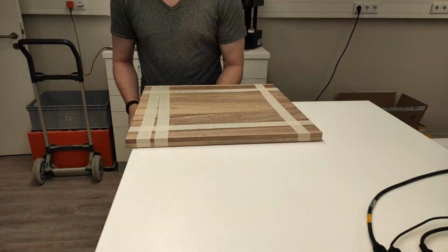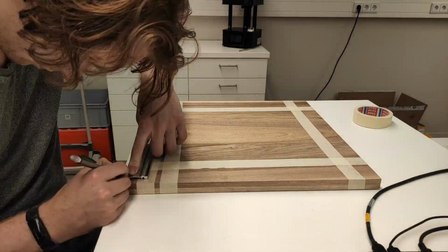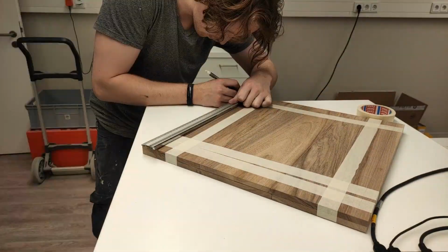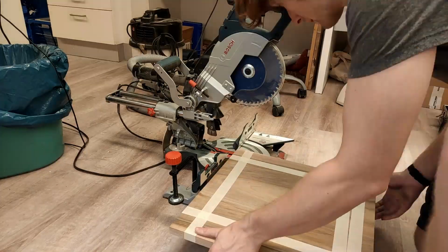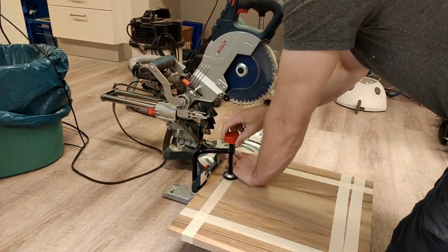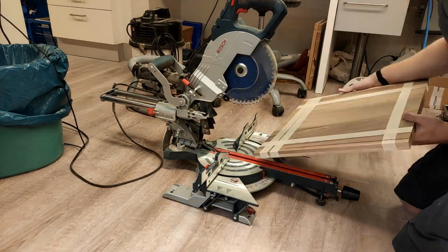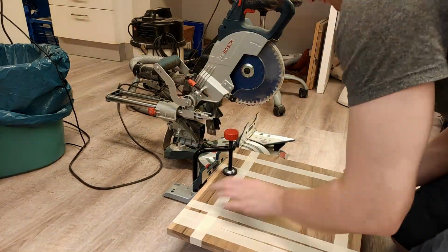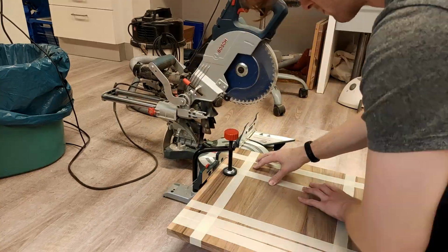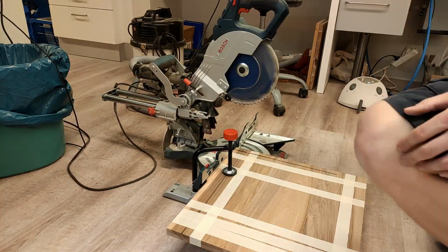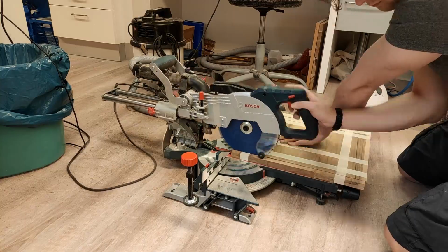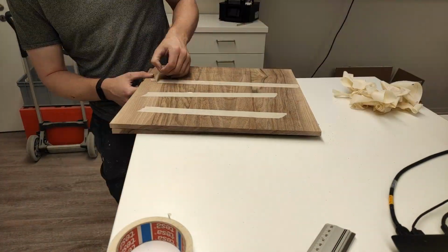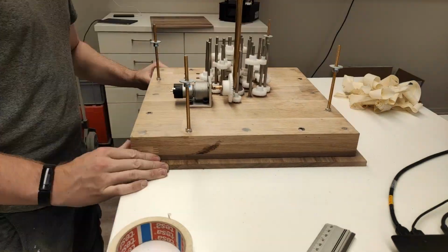One major thing I was struggling with when building this box, which I don't show in the video, is the bending of the wooden plates. But I found a really nice trick online to get rid of bends in wooden boards. What you need to do is make the board wet on the side that is bent upwards and then use a hot iron and iron out the bend. The heat and the moisture will cause the wood grain to expand and therefore bend the wood backwards so that it counteracts the bend from the other side.